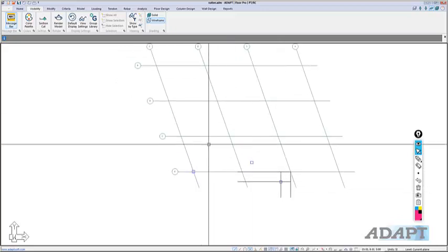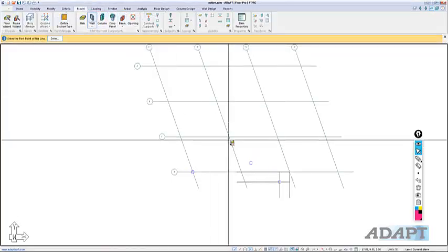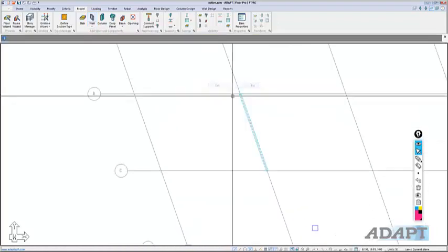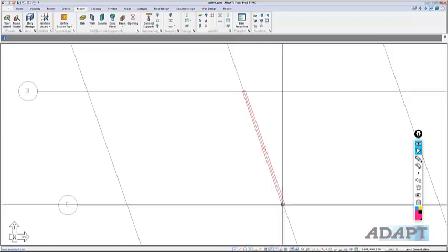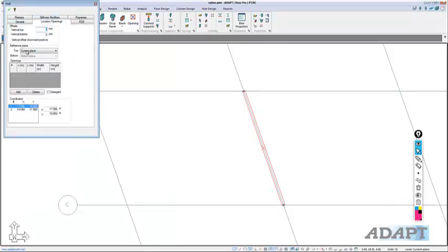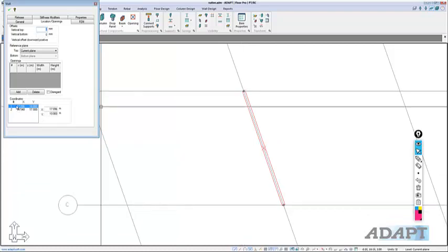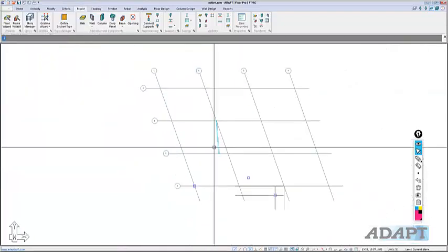And let's create a wall. So we're going to go to Model, Wall. Okay, and I want to move this point of the wall some distance, let's say, in the X direction by 2 meters. So another option you have is if you double click on a component and go to Location, you can always change the coordinates of the wall position. So this is point 1, this is the start point and the end point, and for point 1 we're going to move that by 2 meters, so this will be 15, I'll just call it 15.1, and that realigns the position of the wall.